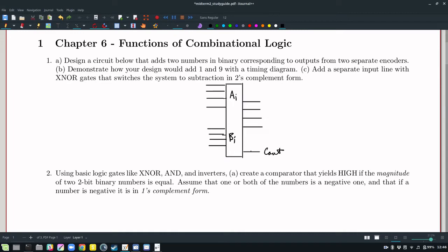Now, in the circuit diagrams in the chapter, you can see that the number of sum bits in a full adder for a 4-bit full adder is equal to 4 plus carry out, and there's also carry in, which we're going to tie to ground. Now, you could put 15 and 15 and get 30, and that, of course, would require 5 bits to represent the number 30, but you do have 5 outputs. You have carry out and then 4 regular.